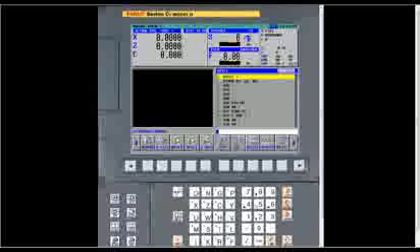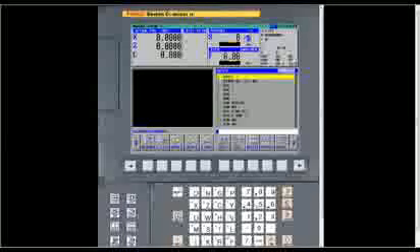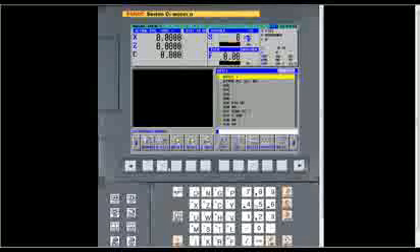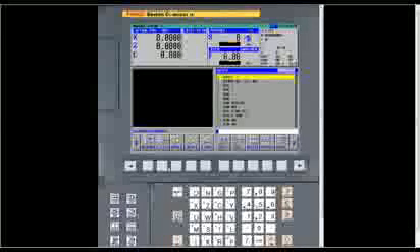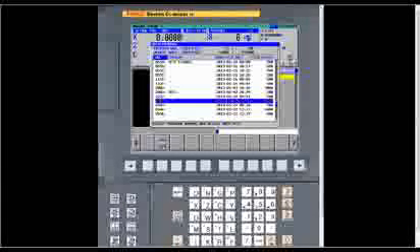Okay. Jody, I guess seeing that simulation sparked a couple more questions. One viewer says, I see the simulation is running faster. Can we get the actual cycle times? Yes. When you have it on an actual machine, now, because I don't have it set up on mine, when you go into the O list, if you go right shift for each, see how it has time here, cut time? When you have it set up totally in your machine, it'll actually give you a cut time and then non-cut time, like for doing tool changes and everything like that. Yes, it will do like a time study for you. And I'm sure that's what they're wondering. Okay, that's a good answer then, Jody.